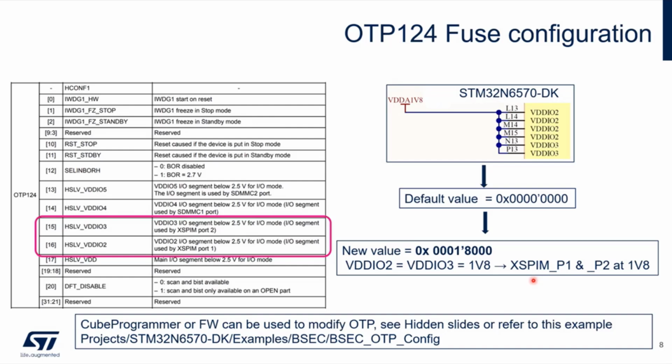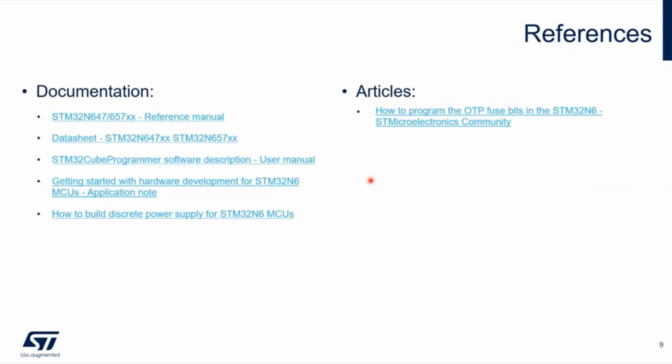What is important here, and a very important hint for you, please be careful when configuring the power supply range, because if we would put here 3.3 volt while the bits are set for 1.8 volt, you can destroy the MCU. We have quite useful documentation.